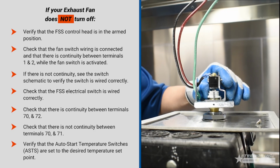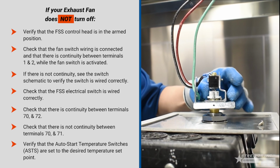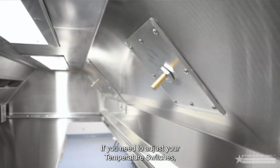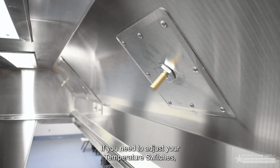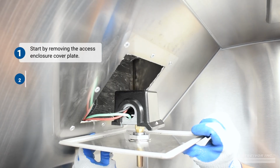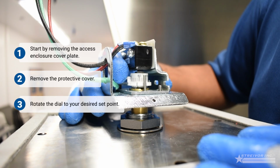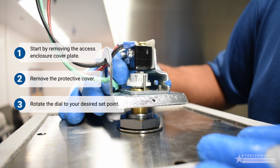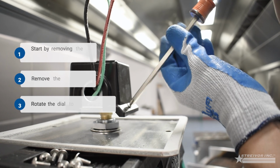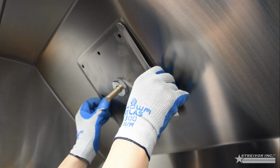Verify that the auto start temperature switches, ASTS, are set to the desired temperature set point. If you need to adjust your temperature switches, start by removing the access enclosure cover plate. Remove the protective cover and rotate the dial to your desired set point. For additional details, refer to our installing and commissioning auto start temperature switches video.